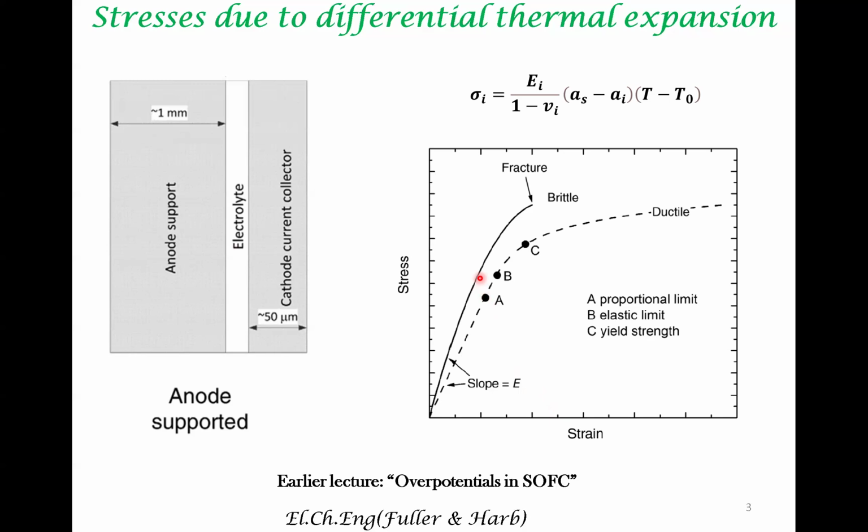The solid oxide fuel cell is typically a ceramic material. It is often brittle. So when significant stresses develop in a particular component, because they are brittle, they may fracture easily. Brittle materials do not accommodate a lot of plastic deformation. They tend to fracture after a particular stress.